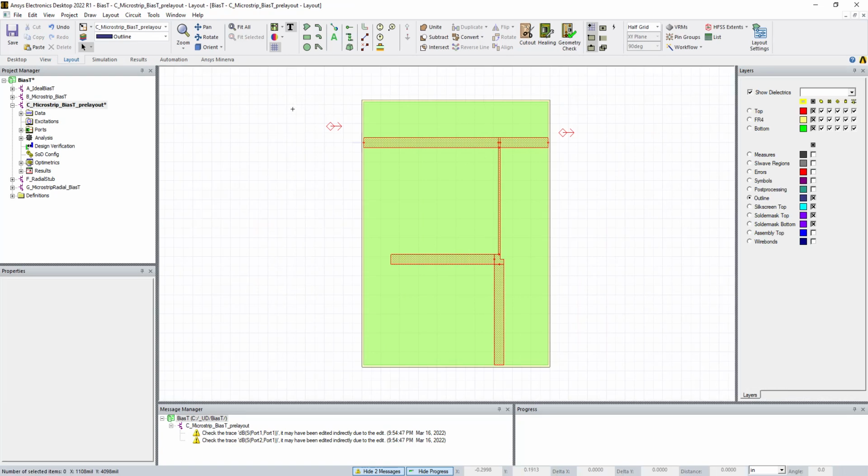So we've done this. Don't forget that when you're on the layout screen, press Control M to realign everything. And I think that's it for video C. Trust me, this will make things a lot easier when we go into the next video. We're going to transfer this whole thing into HFSS 3D layout.